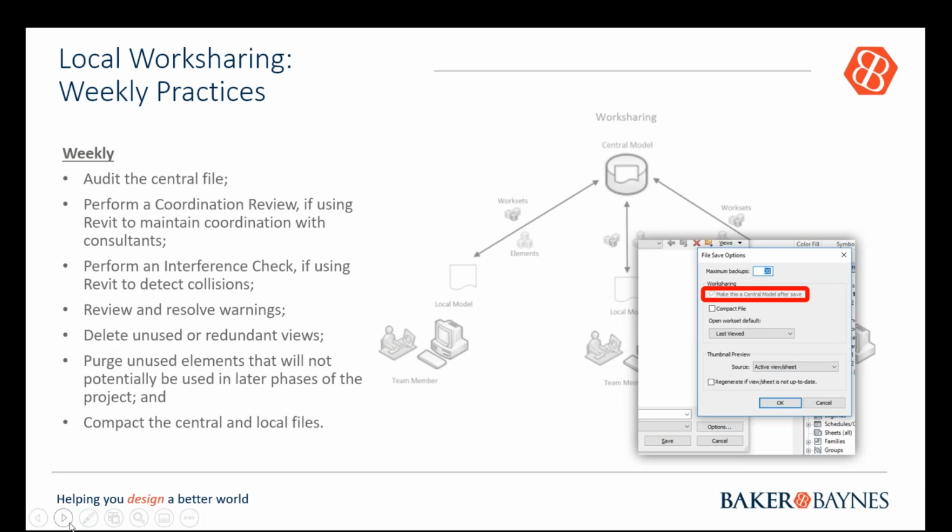So a nice method that I've come up with is to actually create a section line called temp. So you will maybe duplicate the building section line or the wall section line and just rename it to call it a temporary section, and maybe you can change what the head looks like so that you know that it's a temporary one. You can delete it later, and it's best practice to delete it after you've been done with it.